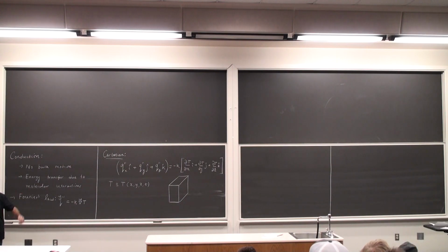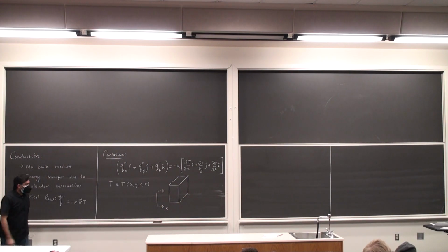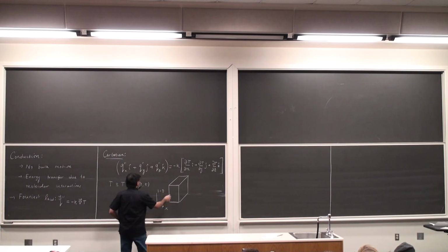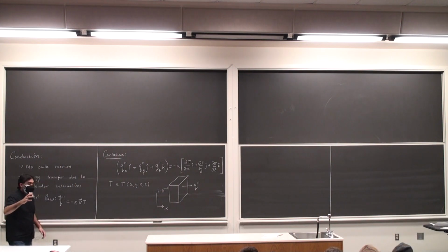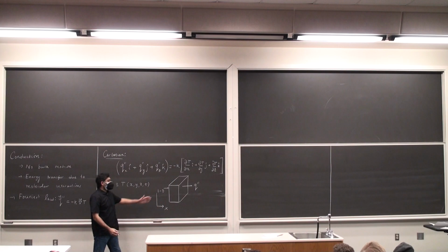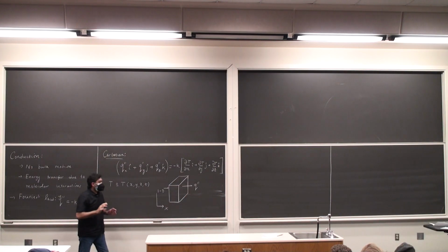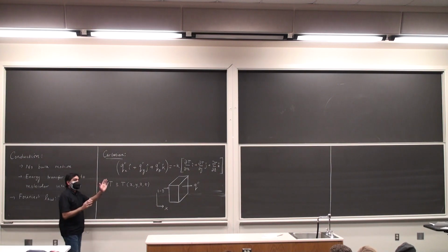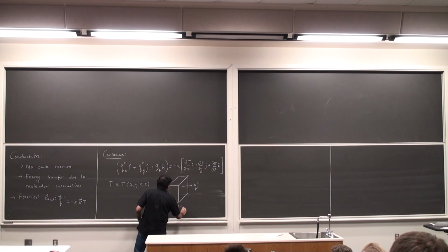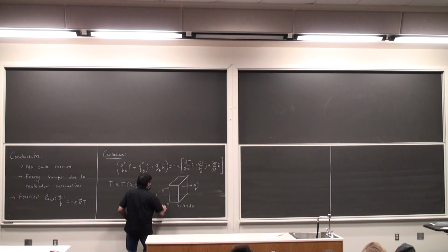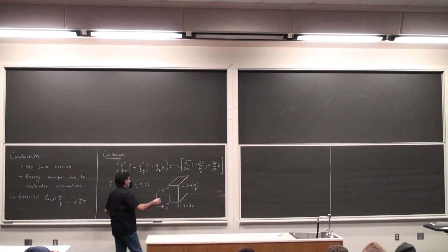Let me assume that heat transfer is one-dimensional. We're going to be focusing mostly on 1D for the time being. 1D heat transfer. Let's assume that heat transfer is taking place from the left to the right. Okay, so q double prime. This is the direction of heat transfer. If I focus on the surface at the left or the surface at the right, it does not matter, it's equally the same. On this surface, what we are implicitly assuming when we are doing one-dimensional heat transfer is that at any point on that surface, the temperature is the same at that x location. Okay, so if I call this x is equal to some x plus dx, and this is some side x, then at x is equal to x plus dx, I'm assuming that at all points on that surface, the temperature is just the same.